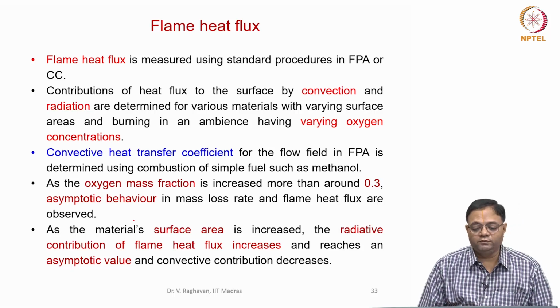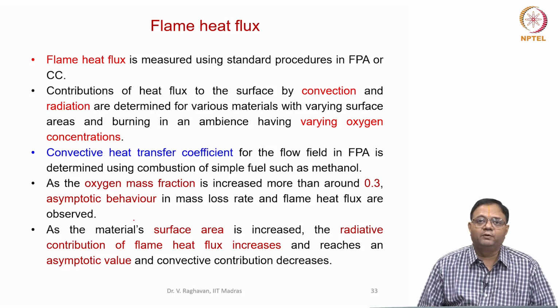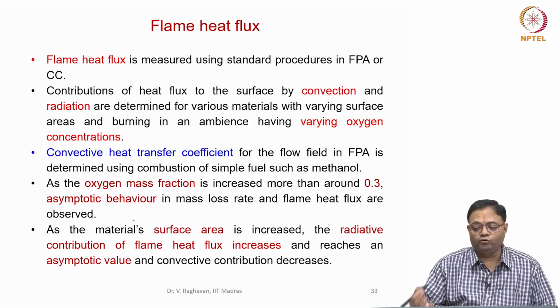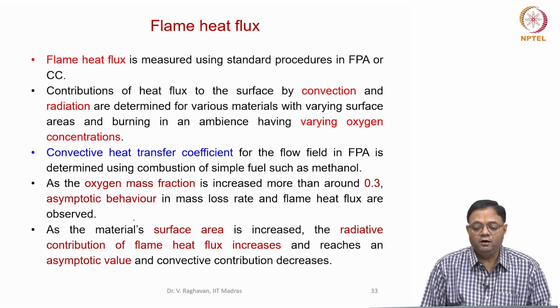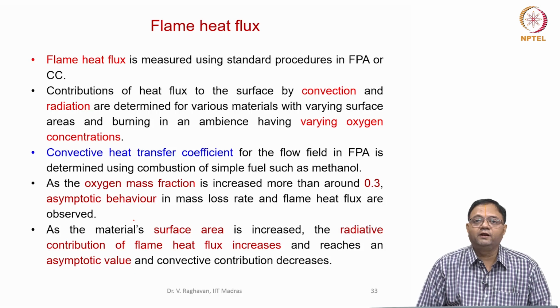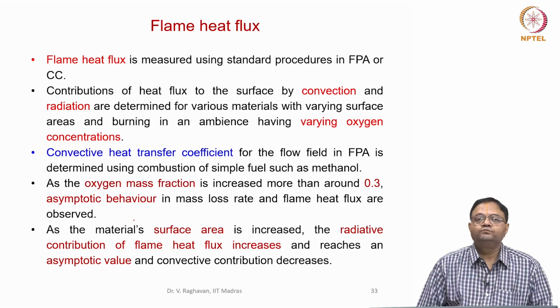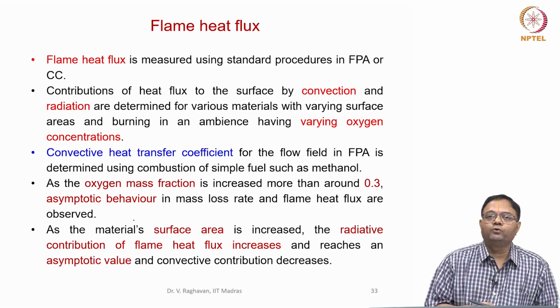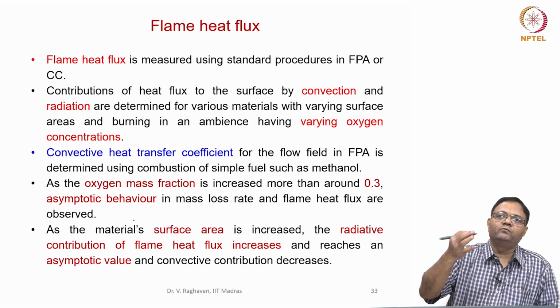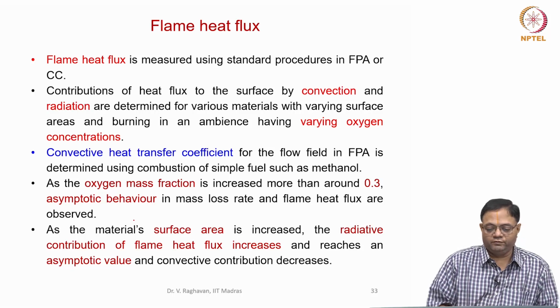So, what we do is, we vary the type of materials, material thickness, the geometry, and also the surface area, and try to burn it, and also we can vary the oxygen content in case of FPA, and know how it is going to affect the flame, how much flame heat is transferred back to the surface.